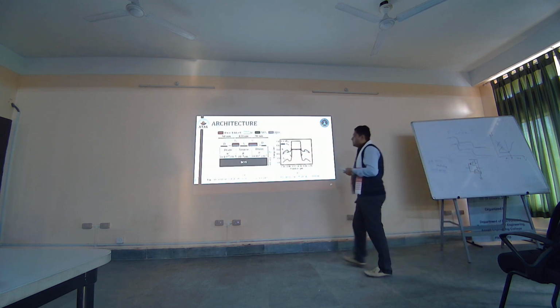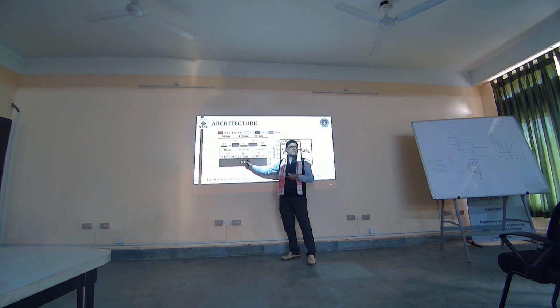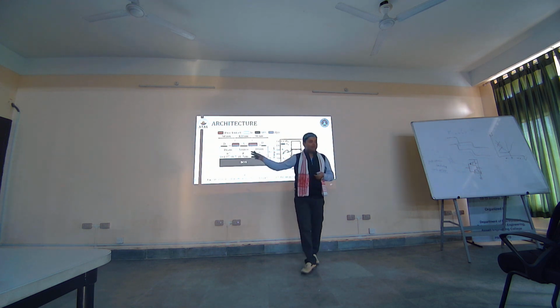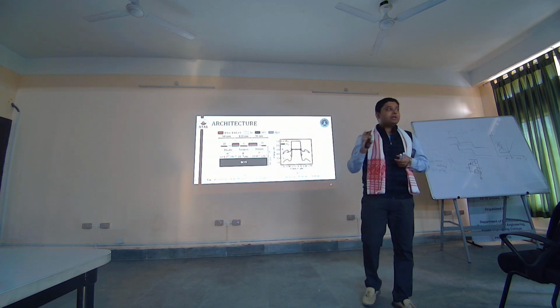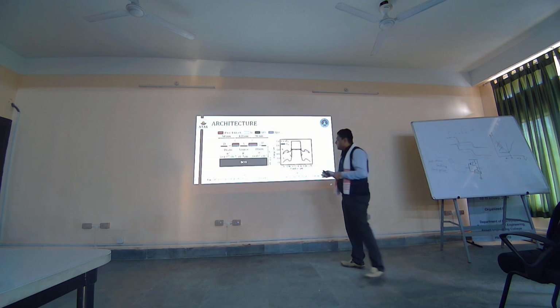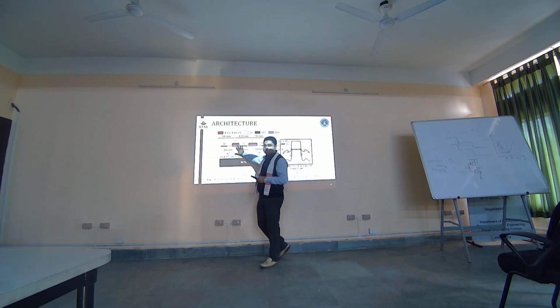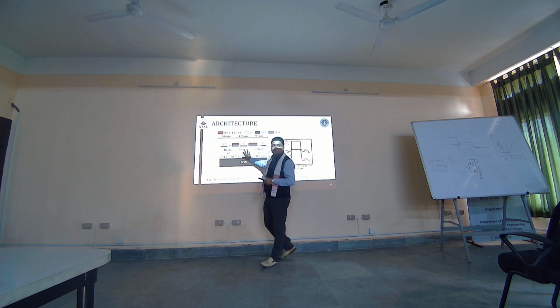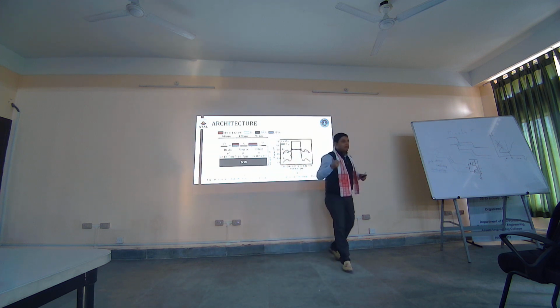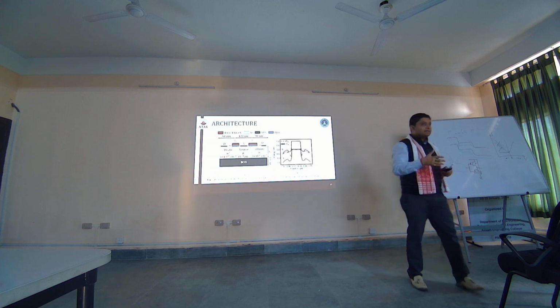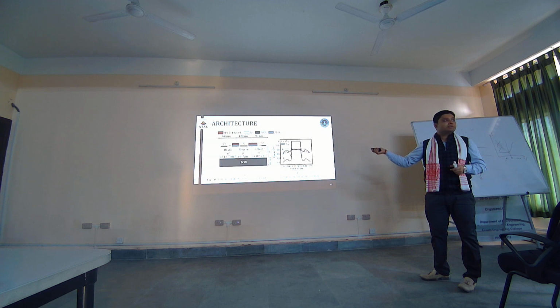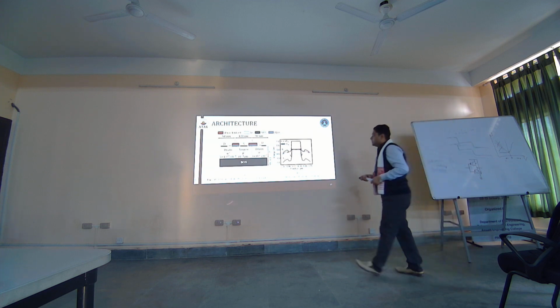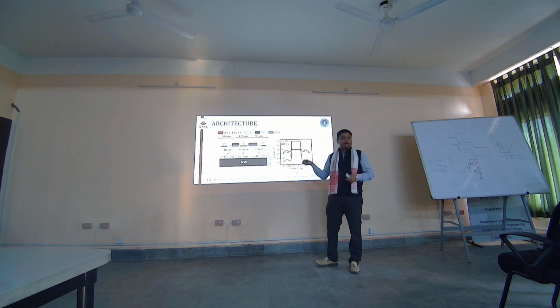If you observe, there is no intrinsic region here, and basically you have only two PN junctions. It looks like a bipolar junction transistor, an NPN BJT. The only difference here is the placement of the gates and the bias. So by altering the bias, and by modulating the doping concentration in the design, we can realize this as a tunnel field effect transistor. Now, the second advantage of this device.